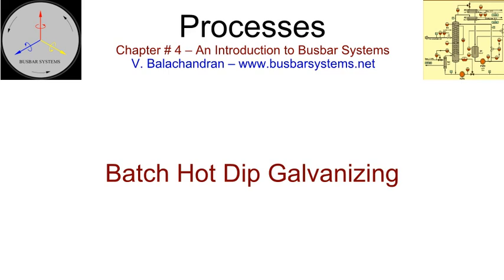The thickness of the coat of zinc is determined by the shape and size of the steel component and time duration. It is a parameter that is best determined by the applicator, based on his infrastructure. The thickness of the coat is always marginally more at corners and edges, which are critical areas. Small objects can be dipped in molten zinc and spun to remove excess deposits to provide a smooth and uniform coat. It is ideally suited for galvanizing fixings, to protect the thread profile.